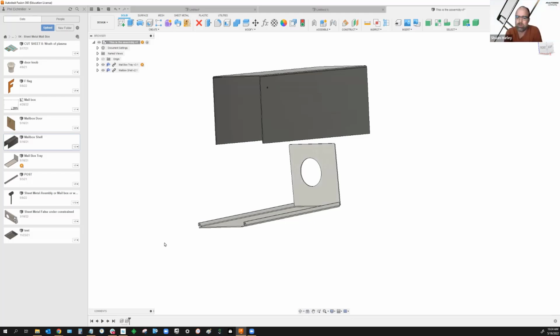Phil? Yeah. George had a question related to this right before you got into this rabbit hole. Why would you use a joint with 0 degrees of freedom as opposed to just an align as you showed? Good question. Okay, so a rigid joint, which is a joint with 0 degrees of freedom, is what you do when parts are stuck together.